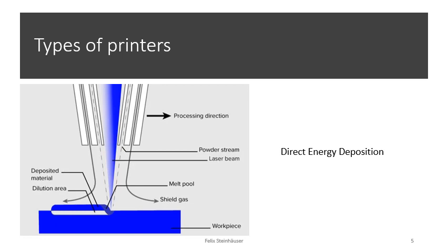This is also one of its applications, where you can use it in a hybrid machine for milling and printing, where you first can mill something in your workpiece and then later add new material through direct energy deposition. But mostly it will just be used to add material to a workpiece, not to build a complete structure on its own.